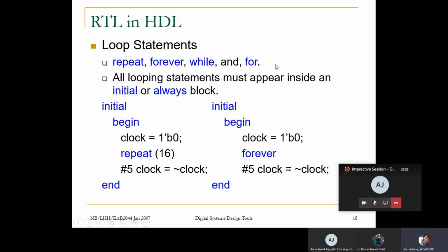Now there's one difference in the for format. Inside the for format, you have the initialize, then your exit conditions, and then your stepping statement. In the stepping statement, Verilog doesn't recognize the increment plus plus operation. You have to use i assign i plus 1.